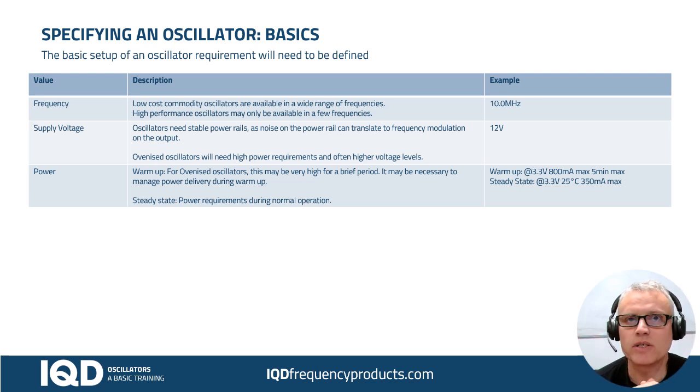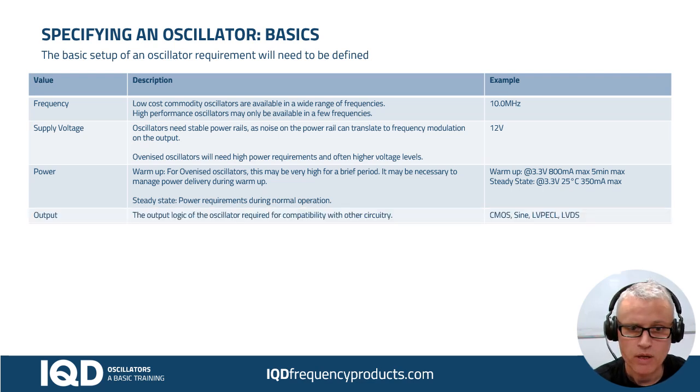I have had a situation once where a customer had a power supply and it didn't quite have enough to give the full range at the moment that it warmed up, and that meant that at the moment it warmed up the rubidium was struggling because different parts of the system were not seeing the same power, and so it never really hit a stable state in its operation because one part had started before another part because it didn't have the right power for it. So there's some lessons to be learned from that.